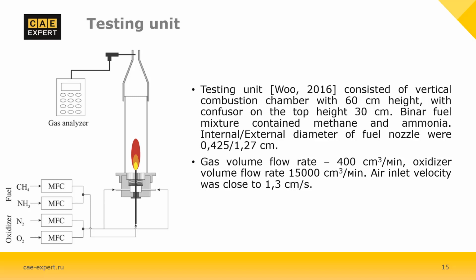A circular cone-shaped metal structure that collects exhaust was installed on the top, and NOx was measured by placing a probe for gas measurement at an outlet 90 centimeters away from the center of the nozzle. NOx was determined by summing nitrogen monoxide and nitrogen dioxide, with the proportion of NO in NOx being approximately 95%.